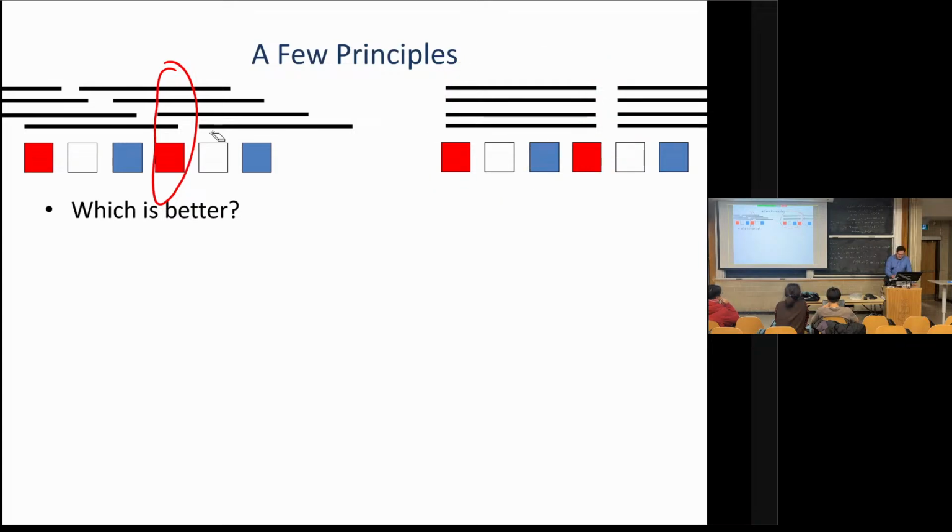Yeah. So basically, this is kind of like what classic hierarchical architectures have. This has got a hard boundary. It's difficult to go across this cut line, but it didn't save me any area. I just stagger the start points of the wires, and I don't actually need any more wires. So I've got more choices. Basically, I can make that blue connection with only 2 wires. And on the other side, I can make the red connection and the blue connection with 1 wire. So without any extra area, I've just got more flexibility.